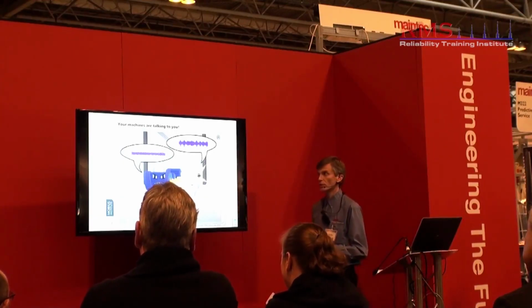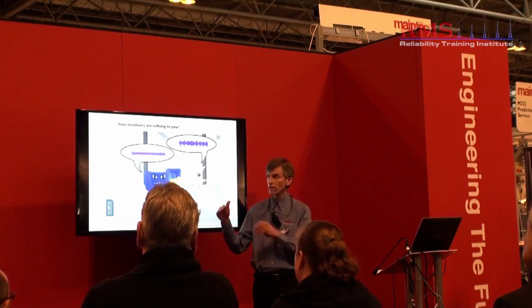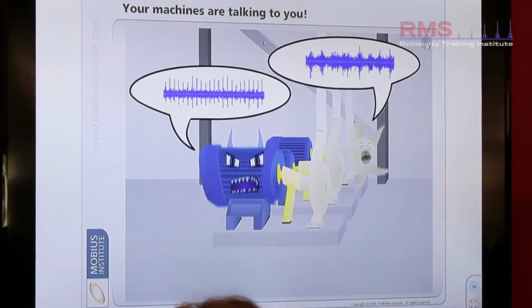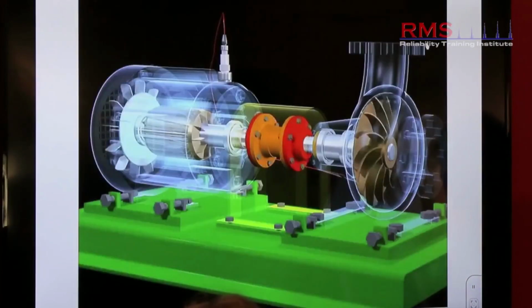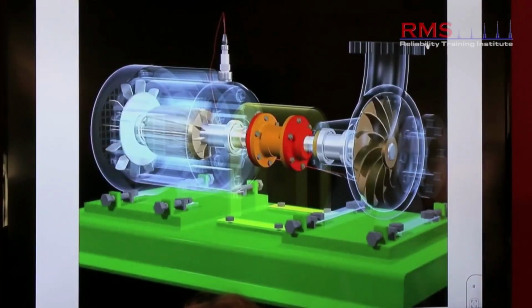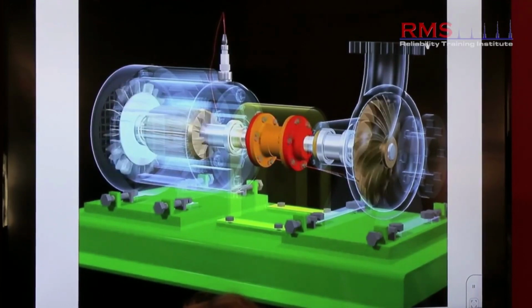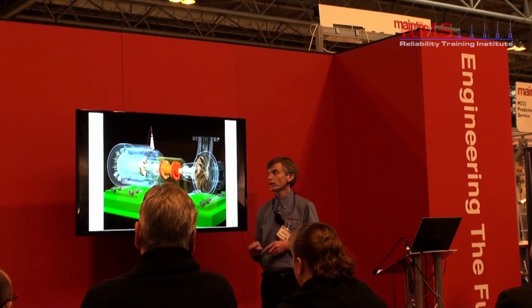So with vibration monitoring, we can measure the signals, we can measure the height of the signal, and we can measure the distance of the event, how long each event takes, to understand which component in the machine is problematic. So we can narrow it down to a specific component within the rotating asset. Here we have a sensor placed on the machine.